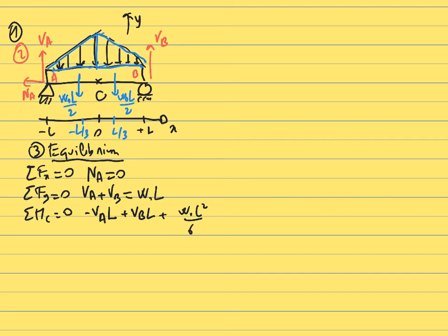And then finally, we have the moment created by the distributed load that goes between 0 and L. This one will have a moment that has a negative projection. It's going to be a clockwise moment. The intensity of the force is also W0L/2 multiplied by the arm of the force, which is L/3. So you find the moment is W0L²/6.